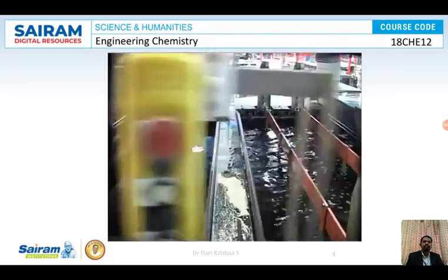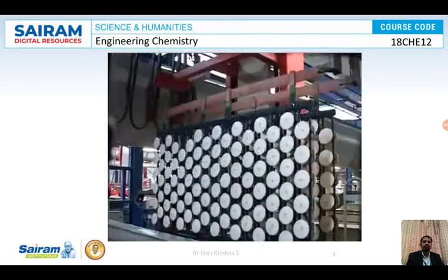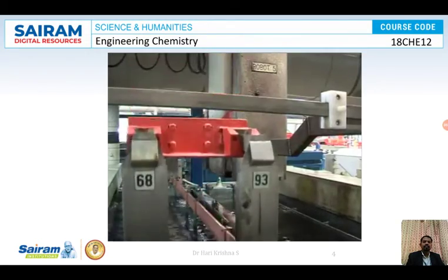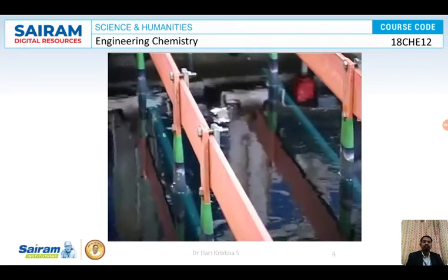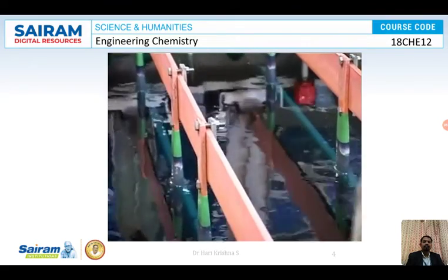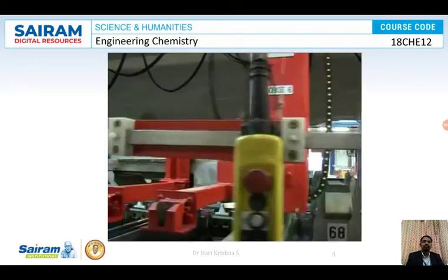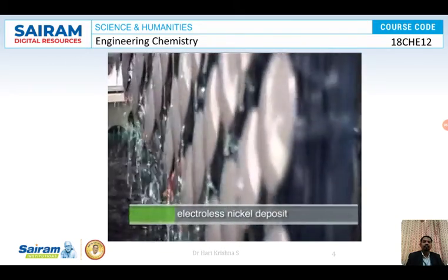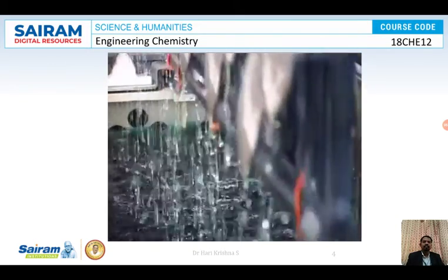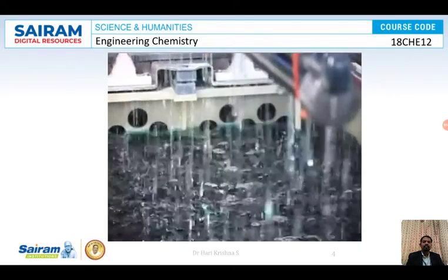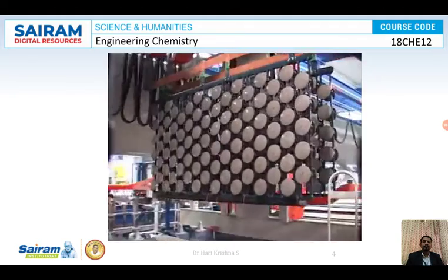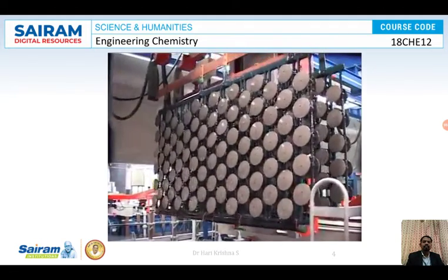After acceleration, the surface is ready for a thin layer of a conductive metal to deposit on the palladium catalyzed surface. This occurs from an electroless nickel process step, which deposits a thin, dense nickel phosphorus alloy. The nickel alloy layer thickness deposited from the electroless nickel ranges from 0.2 to 0.4 microns, resulting in the plastic parts becoming conductive, which is very important for the deposition of the copper, nickel, and chromium electroplating sequence.